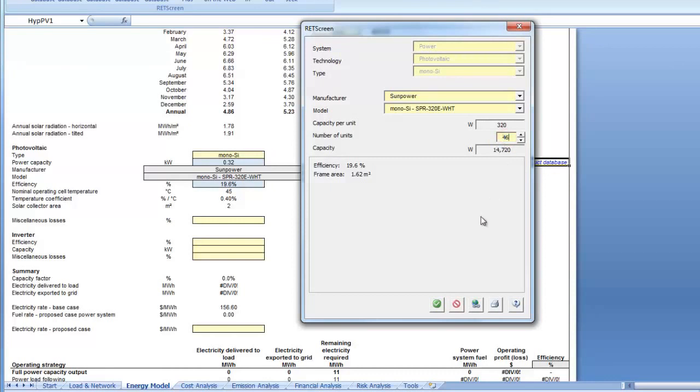Lower costs can easily be obtained thanks to economies of scale such as system aggregation, and with solar carports, we can also expect to see a reduction in labor costs compared to the average rooftop PV system. In order to make this project more viable, the system capacity should exceed the residential load plus the load attributable to 1 or 2 electric vehicles over the next 25 years.